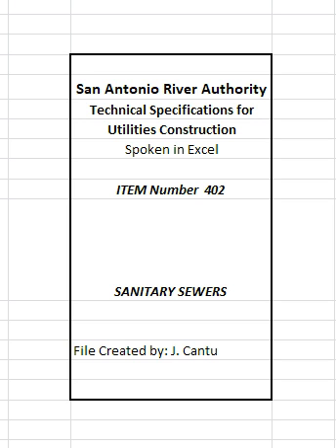No pipe installation will be accepted until all known leaks have been repaired, whether or not leakage is within allowable limits. Locating and repairing of leaks shall be performed by the contractor at no additional cost. The engineer will certify that all required pressure and leakage tests have been successfully completed before the pipeline is accepted. The engineer's records will include the rate of leakage of all final leakage tests. Passage of a test does not relieve the contractor of his responsibilities to meet the requirements of the specifications.